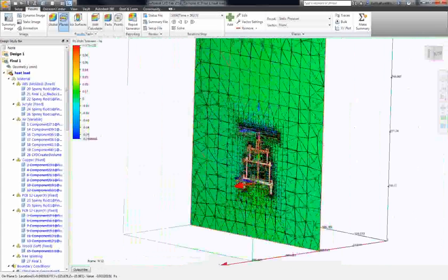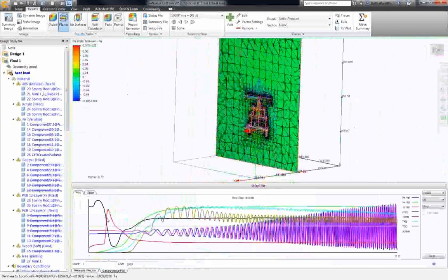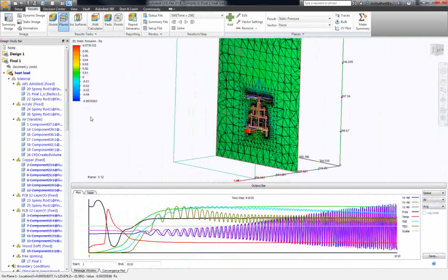One thing to be aware of: there was a mention from Scott about the CFD2 solver in 2017 beta. If you ever use the CFD2 solver, you will see that we actually use tetrahedrals along the wall elements. So that'll be a change. Prisms will kind of go away and everything will be tetrahedrals. There is also, if you use extruded mesh, then of course you're going to have more of an extruded element. You're welcome. I'm glad that was helpful.